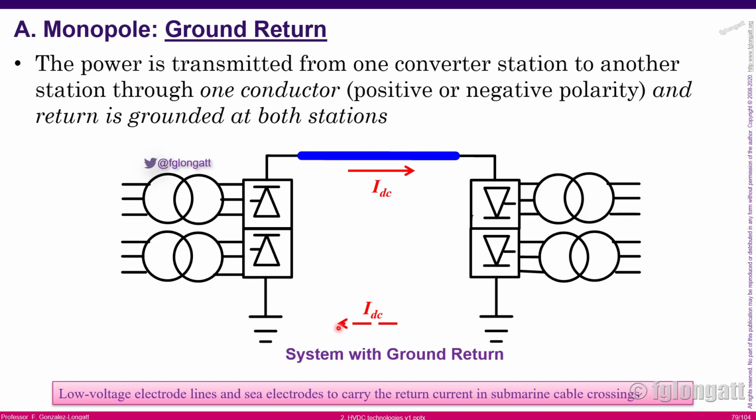Advantages and disadvantages. The ground return involves the ground, and you don't have full controllability over the grounding resistance, okay? And there is a possibility of a bigger voltage drop across the grounding return, okay? But the other issue regards those electrodes. Those electrodes will receive a lot of current at the converter station, and as a consequence, the electrical stress over there will be high.